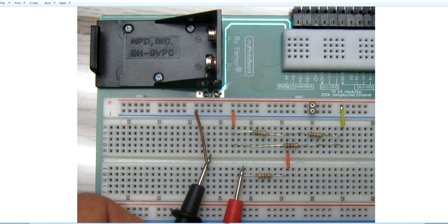We've effectively connected the inlet port for power along the red strip. We've jumpered it to ground, ground being where I'm running my cursor across. Notice the load resistance has been taken out where I'm running my cursor horizontally. And I place my two probes once again, my red, my high probe, and my negative probe, across the positive end, across the outlet end of resistor 4, and the negative probe effectively to ground.